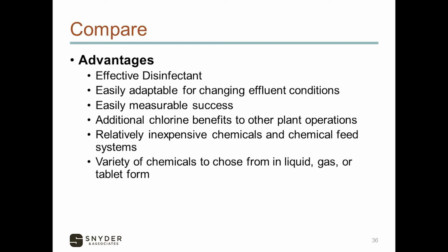Let's talk about advantages and disadvantages of chlorination and chlorine disinfection systems. Well, it's a well-established technology, and quite honestly, I have great faith in its ability to do the work. Even when your plant isn't running very well and your effluent looks terrible and UV could never do the job, chlorine can do the job. Normally, you might feed 2 milligrams per liter, but if it won't make the requirement at 2, okay, we can feed 10, whatever it takes.